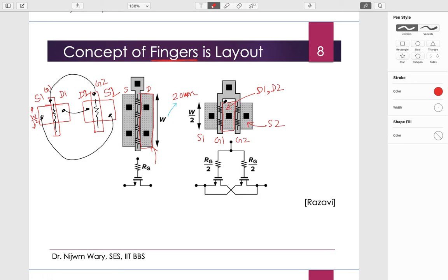Why? Because of this overall area reduction, the capacitance associated with the drain reduces, and you know that capacitance impacts the speed of operation. So this also helps to increase the speed of the device. Now you may say, what's happening to the source? The area of the source is in fact increasing a little bit, and because of which the parasitic capacitance may increase.